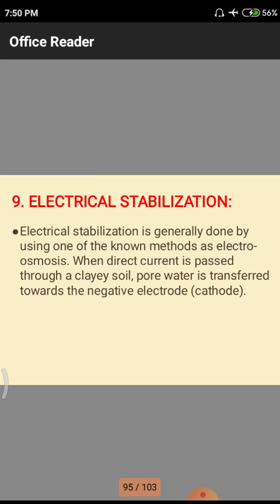Due to the maintenance of slopes and cambers, automatically by the action of gravity, the water is collected at certain points. From those points, we use boreholes. From the borehole, we simply collect the water from the soil, so that the water present in the soil will be removed with the help of engineering principles. But in the case of clay soils, this is not possible.